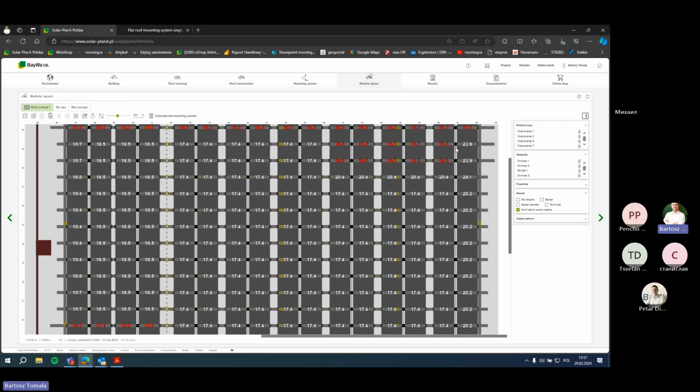So we have over 20 meters of the material combined in one array. It will be too much for this construction to be completely sure it's safe. These thermal expansions could destroy, for example, modules if they don't have the place to be compensated. That's why we use this expansion joint.